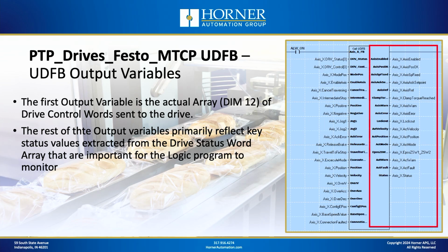And then pretty much the rest of the output variables that are assigned are variables you can monitor that show you what's happening in the drive. All right, so the UDFB is generating a bunch of useful, mostly monitoring data that you can use to see that the drive is reacting the way you want. If there's any faults, you'll see that. If you've got a home reference, you'll see that, those sorts of things. You'll see the actual position, you'll see the actual velocity, those sorts of things. So other than that first output array, the rest of those output variables are ones you're going to want to monitor and use elsewhere in your logic for that purpose.